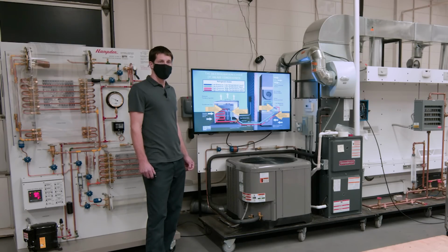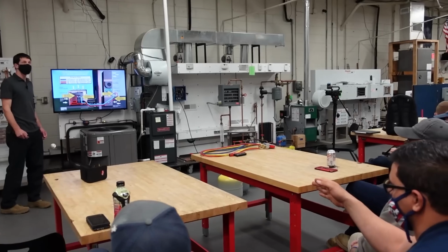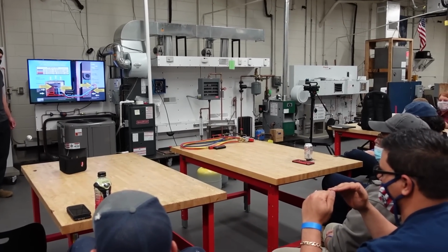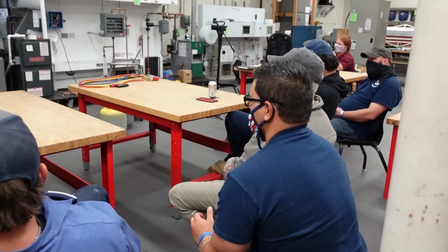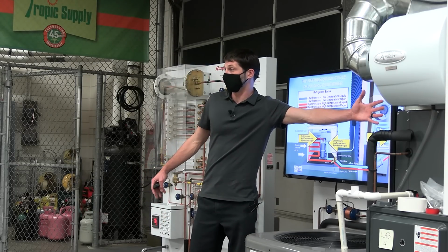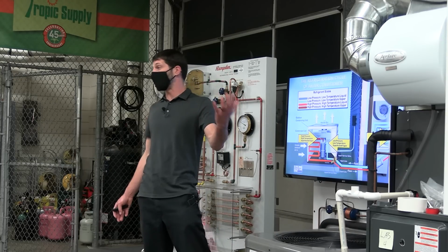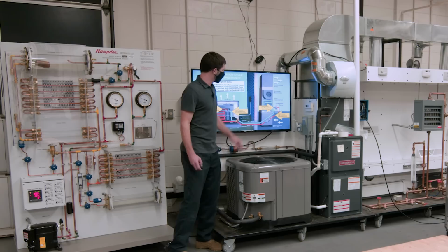And in refrigeration, that comes up a lot. Yeah. When the fixed orifice is not as effective, it's because I guess the pressure drop is not as big as when you have the TXV. So what happens when you have a high heat load in the building, say it's like 80 degrees, or maybe it's even 70 degrees, but it's real high humidity, what happens is the piston is not going to allow more refrigerant into the evaporator coil.